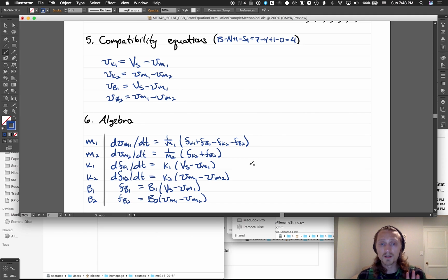We have a fourth order system, so we're looking for 4 differential equations to end up with. These 2 are algebraic equations, they're the extra ones, but they're solved for the primary variables, Fb1 and Fb2, that we need to insert into these equations above in order to eliminate non-state and input variables. The 4 differential equations that we should end up with should all be in terms of state variables and input variables, and derivatives thereof.